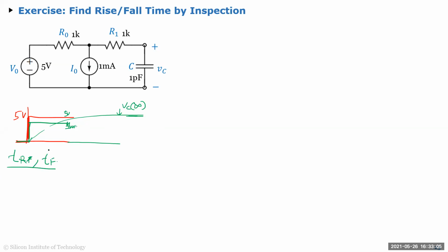Let me give you a couple of minutes. And like I said, don't try to solve the network equation, but do it by inspection, in the sense that you convert it into an equivalent RC circuit or whatever you can, and then tell me what the rise time and fall time would be.